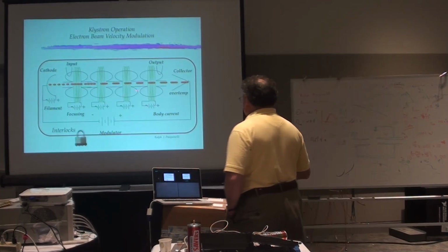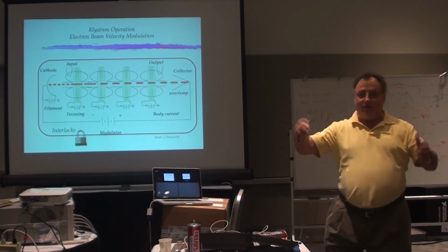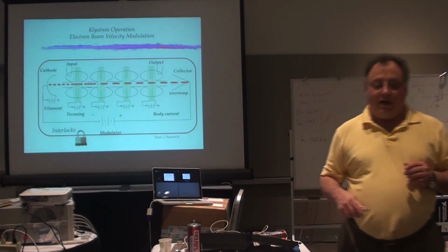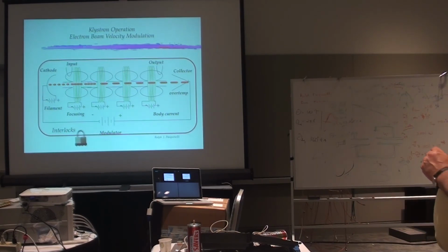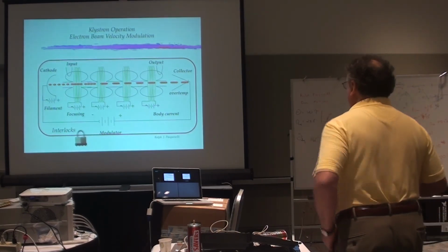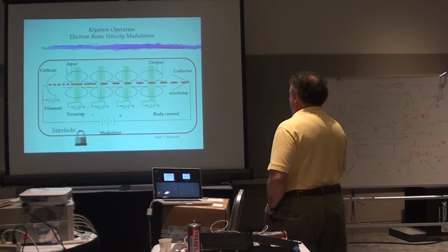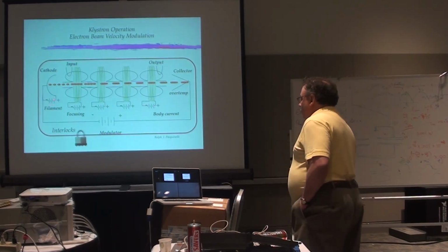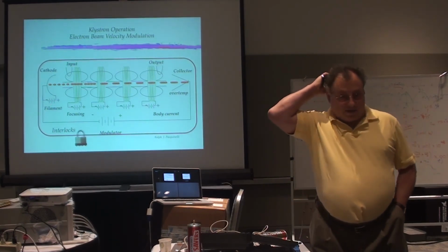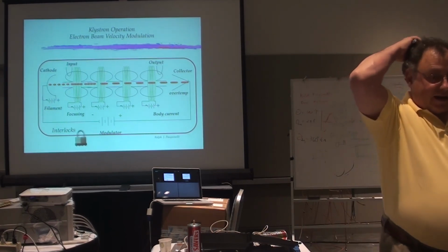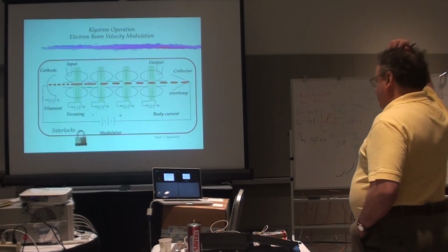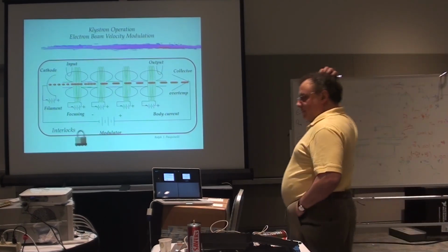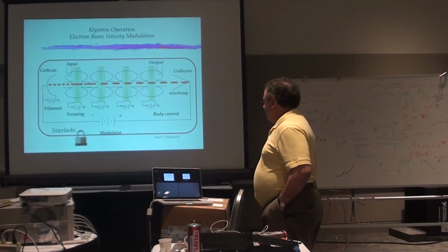It needs solenoidal focusing, so every single one of those cavities has a solenoid around it, and those things can chew up an enormous amount of juice because they're electromagnets, but that allows you to tune the lattice to make it functional. You've got a filament voltage over here, which is substantial. I think I said the other day, in our LINAC at 201 megahertz, a 5 megawatt triode is the output stage, and its filament runs at like 3 or 6 volts and 7,000 amperes. So that's a serious beast.